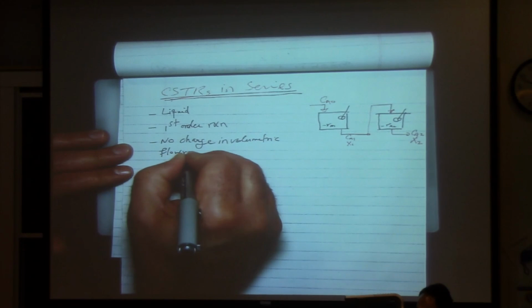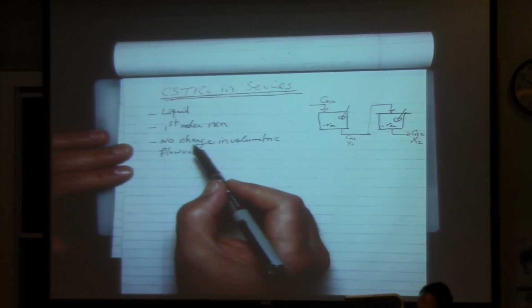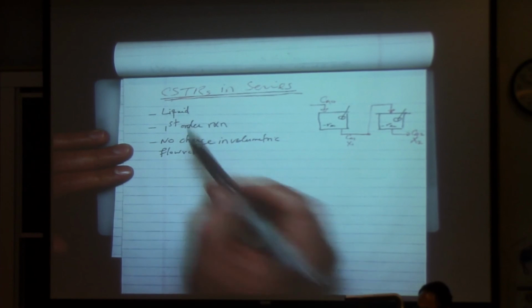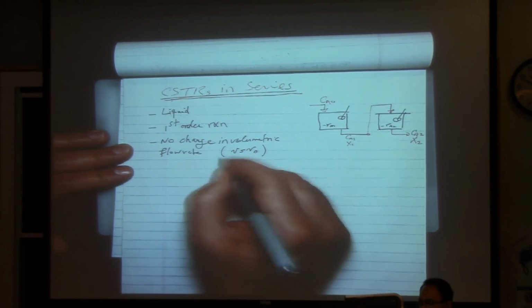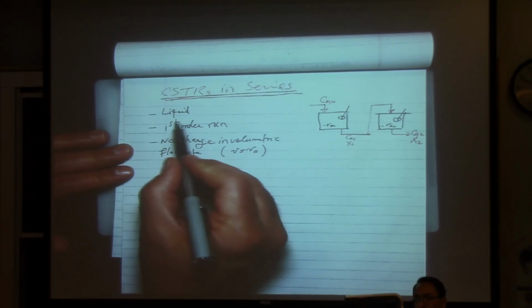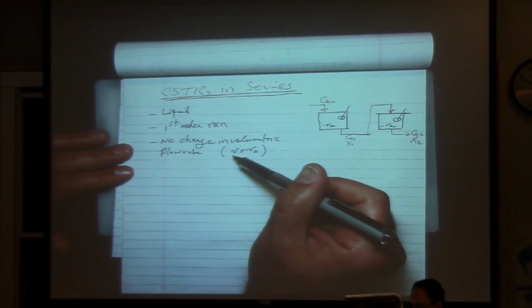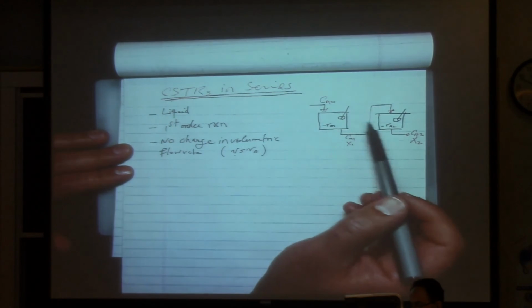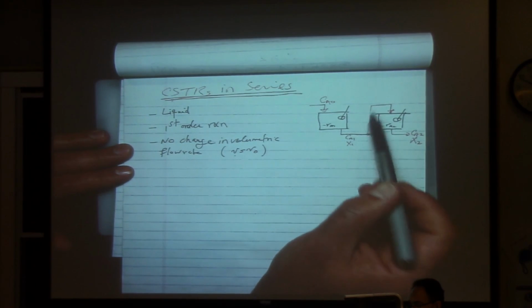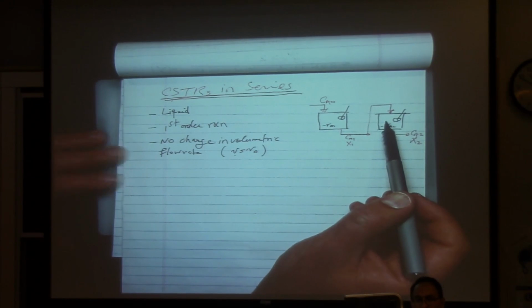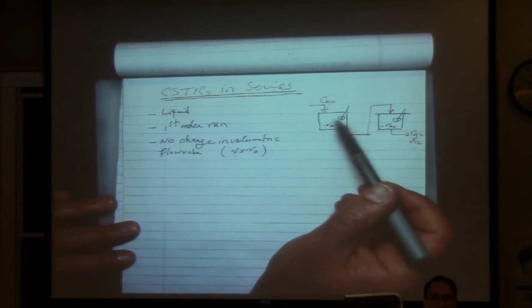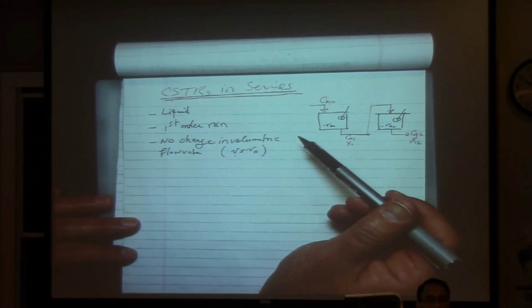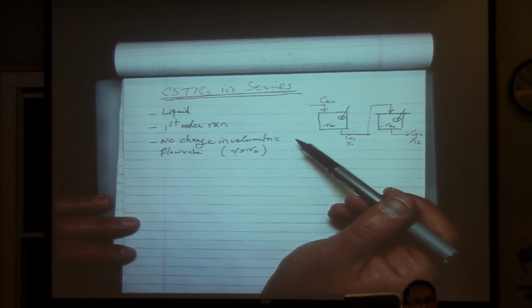That basically means you can imply this from this being a liquid. So it means that your V is equal to V0. You are not changing the volume, which is obvious when you are dealing with the liquid phase. Sometimes, even in a liquid phase, the volume through the second reactor may change because of resistance and other things, but these are cases when you are dealing with pressure drop.